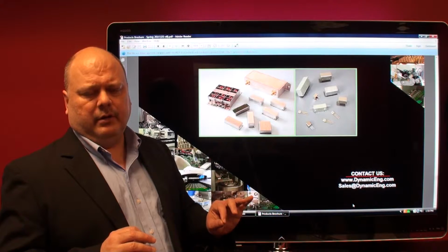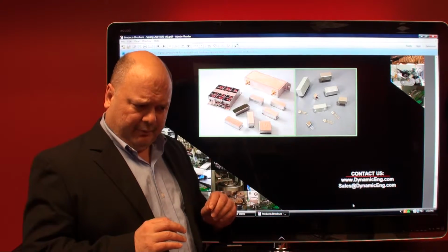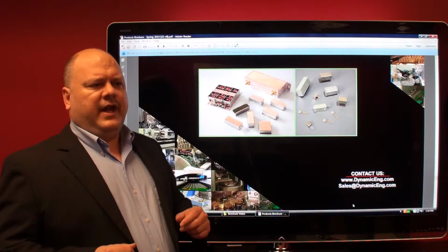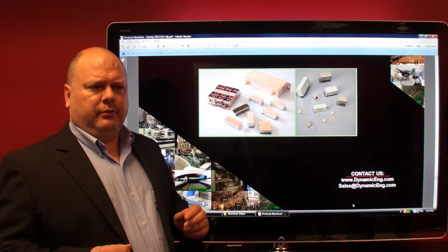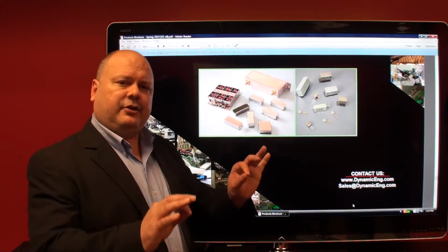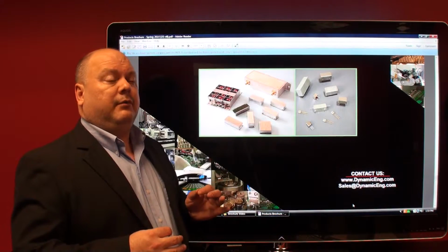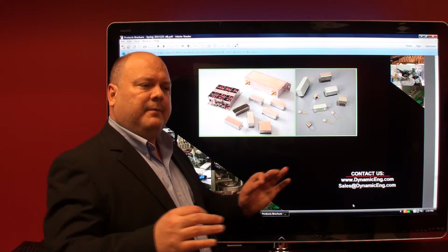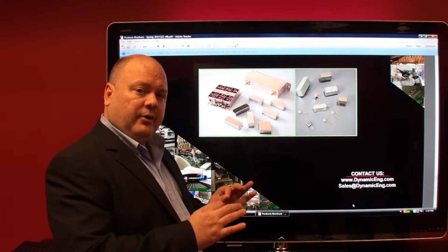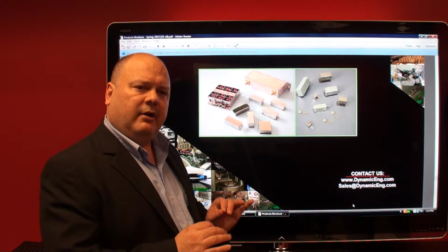secret of the operation. So there are, believe it or not, filter houses, filter manufacturing operations that have no crystal manufacturing capability at all. They try to assume what the relationship is going to be between finished crystals. Then they buy finished crystals from the outside world. They think they're saving themselves cost. But what's really going on is they have to basically scrap all the crystals that they can't match up with each other inside a properly matched filter unit. So their scrap costs become very high.